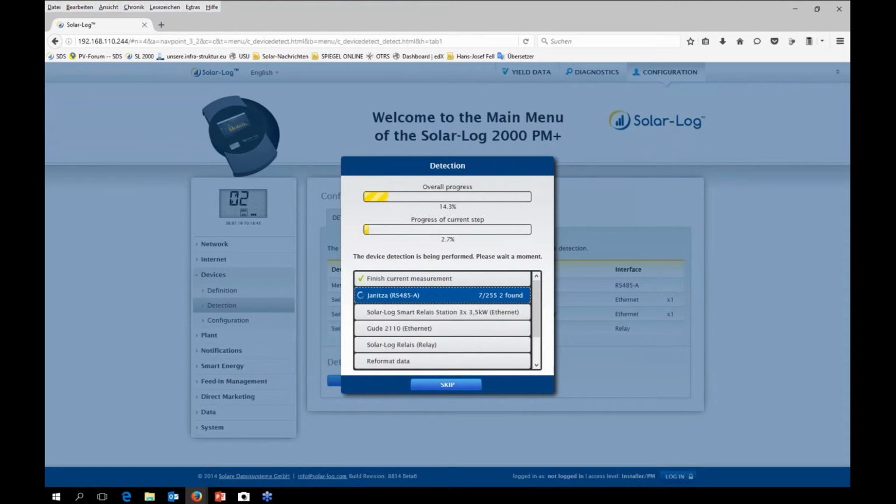I see one question I can answer about the regulation value in watts, related to AC or DC. So it's the percentage. The regulation value in watts is AC, because we measure and take care of the AC. This is important for the grid. The DC values are not so important for the grid issues.